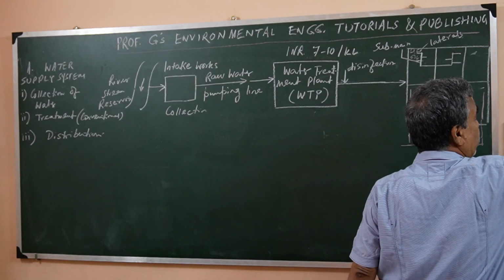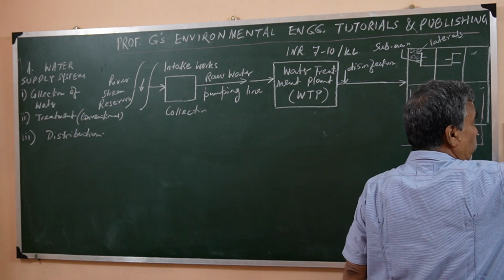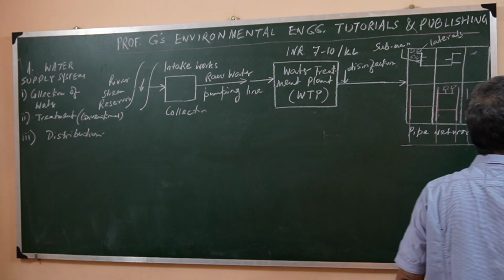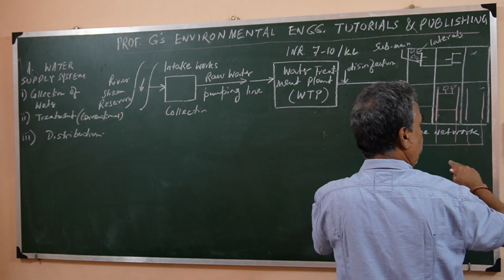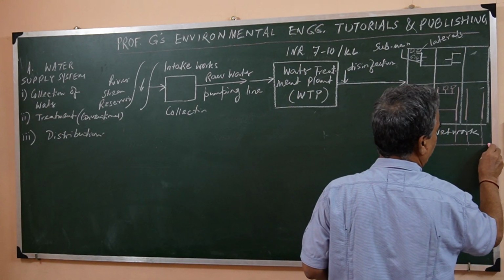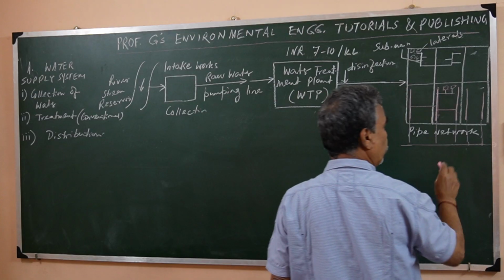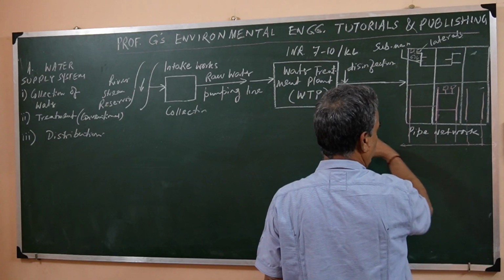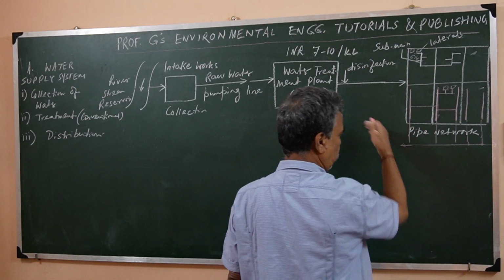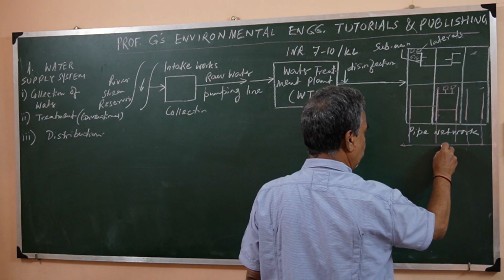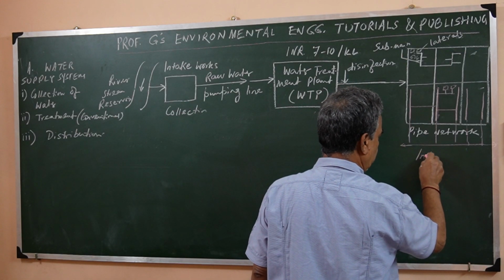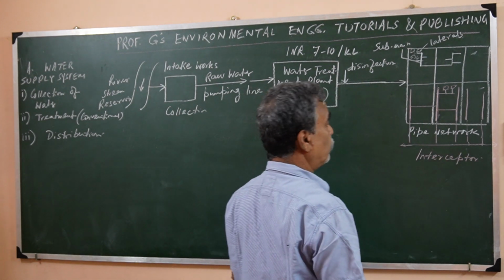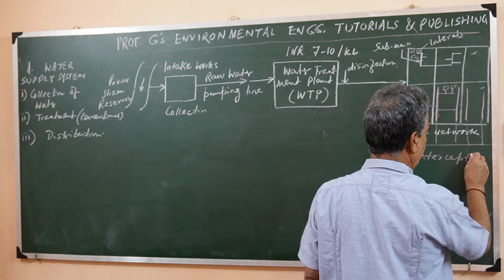So in other localities also the sewage or the wastewater is collected from the respective sewerage network, and all will be integrated. So here I am continuing this one because of the shortage of space. This side also may be some other localities, or the cluster also. So these are intercepted, that is the intercepting sewer. Let us rather modify this to intercepting.